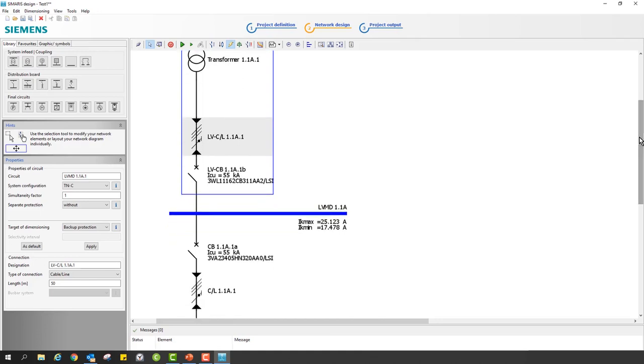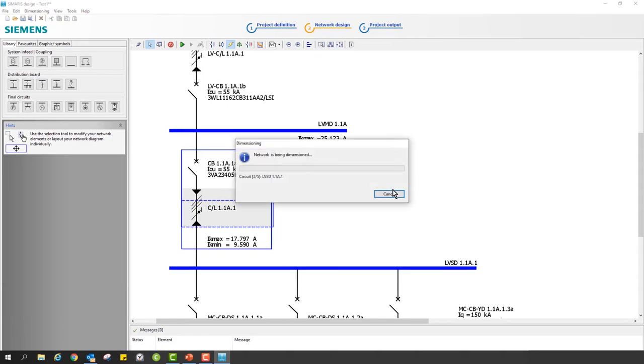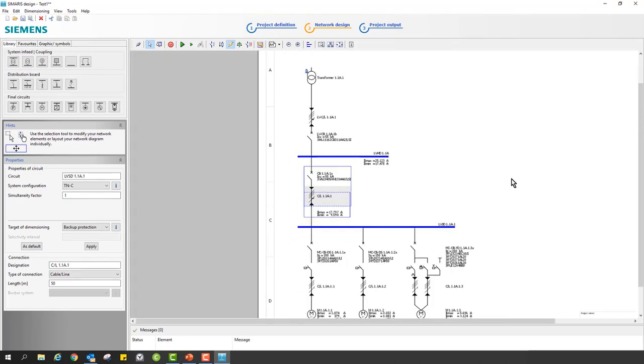Now let's imagine, as you can see here, that I will need to comply in my control panel with 26.7 kiloamps. What will happen actually if this won't be at 20 meters length, but actually 50 meters length from the transformer? What will happen now? Well, you see this is calculated again, and the short circuit currents have also decreased once again, meaning the cables can attenuate the short circuit current rating. Yeah? Especially now, let's see in our control panel, we have actually 20.